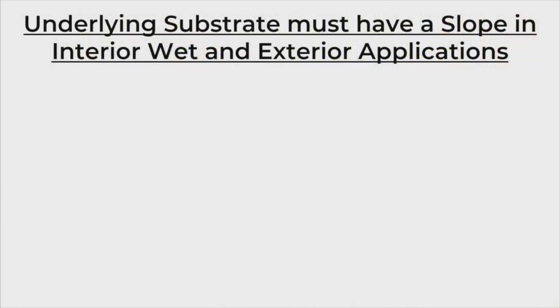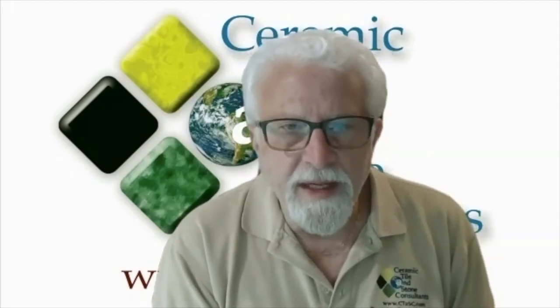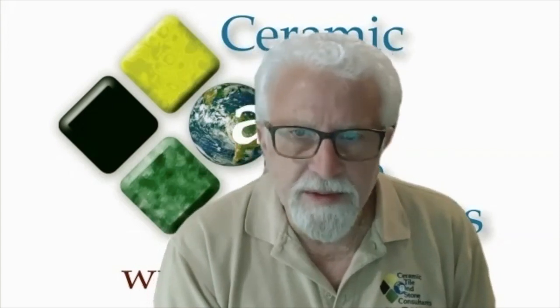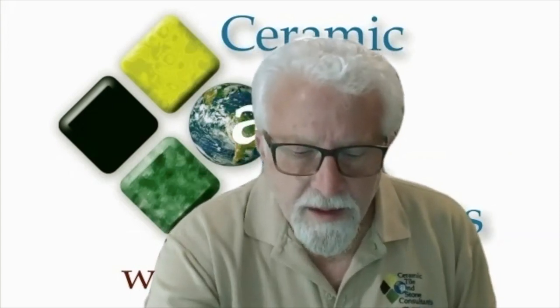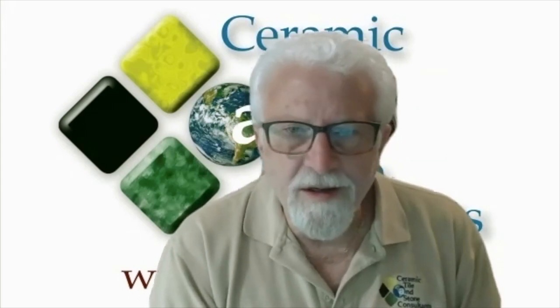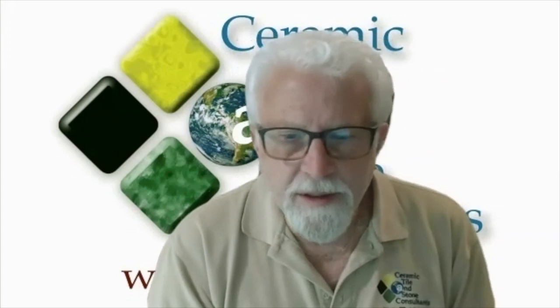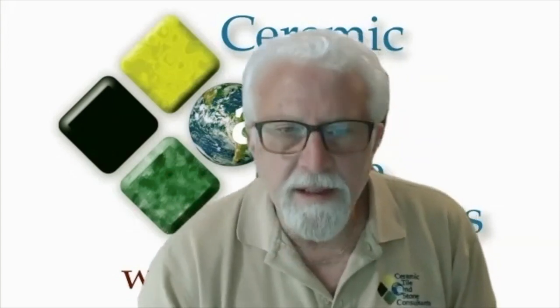The underlying substrate must have a slope in interior wet and exterior applications. I've talked to you guys before about this. This is really critical. We see a lot of problems of improper design of substrates, particularly in wet areas such as a shower or an exterior deck application. What's critical is, there are several things.